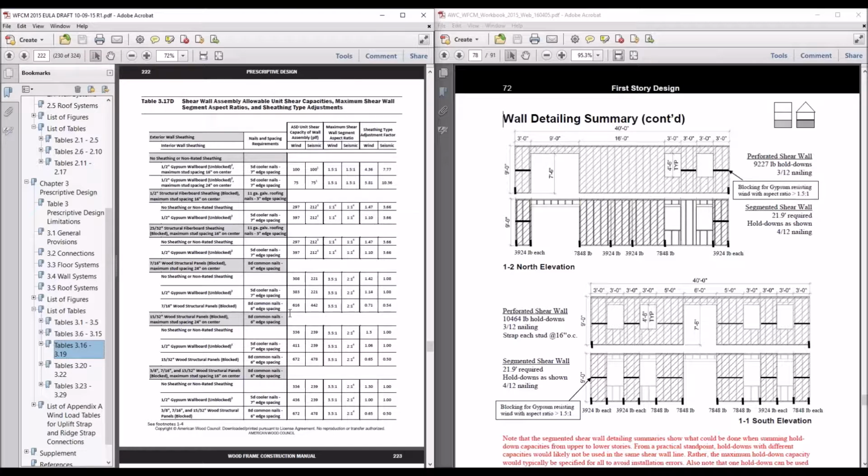So if, for example, you're laying up your panels vertically and you want to break across the band joist and break at the lower part of the second floor, then you could break at the 2 or 3 foot mark of your second floor. The thing you got to watch out for there is shrinkage of your band joist. So that's something that you need to be careful of if you're using the wood structural panels to resist uplift and shear.